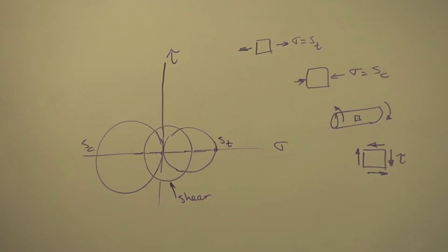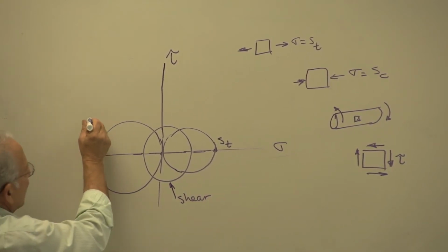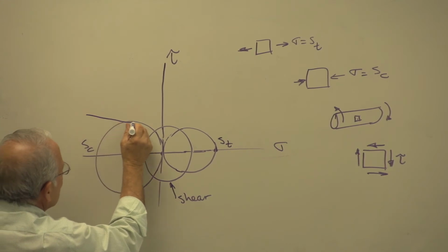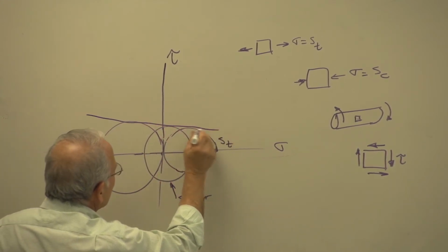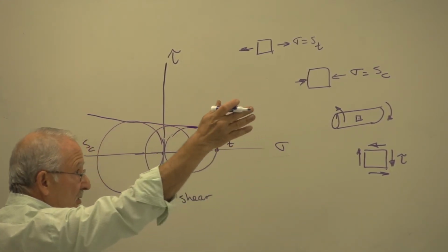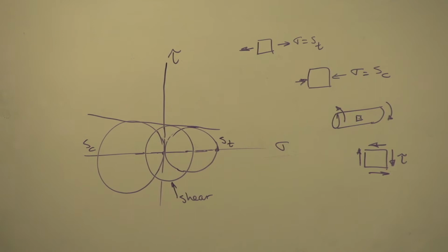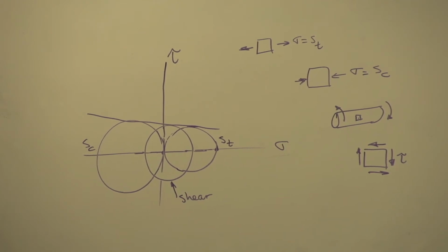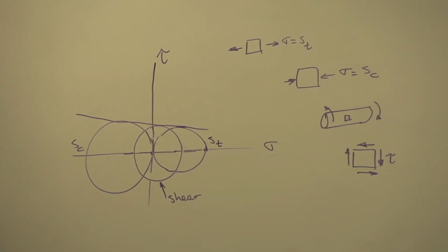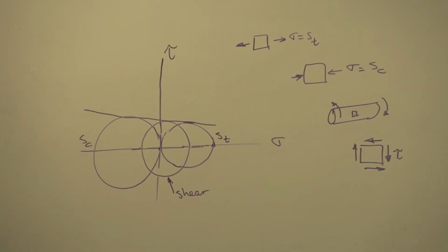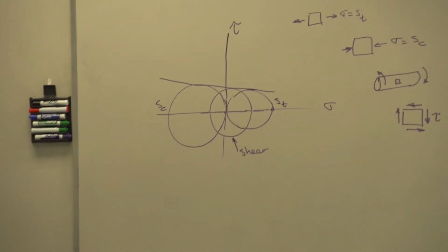And if we now draw a curve such that it is tangent to all three of these, similar to curve A, B, C, D, E shown on the screen, that curve is the limiting value of any Mohr circle of this material tested in any way.